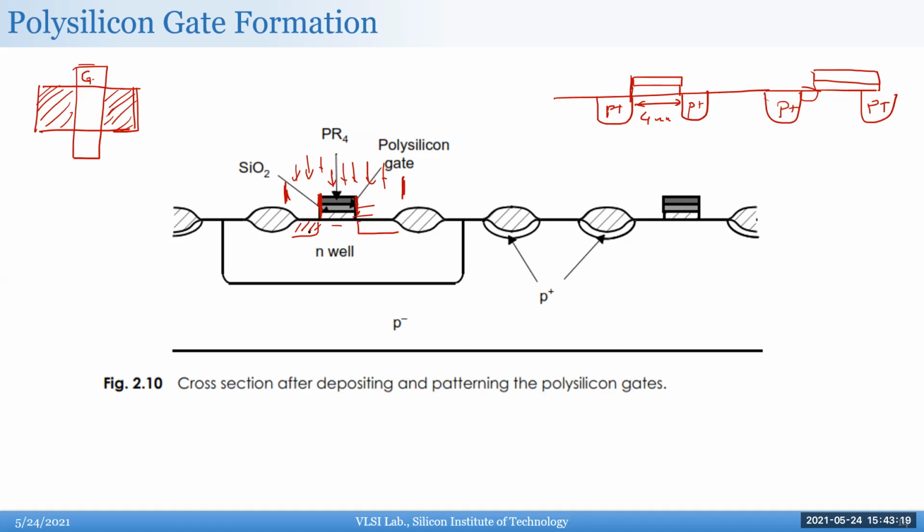But in the self-aligned process, it's very difficult to do metal. In fact, you can't do it, and that's why they use polysilicon. But polysilicon is very highly resistive. But the thing is that when the ion is bombarded, so let's say you are bombarding with some positive ions, those positive ions also get bombarded into the polysilicon.